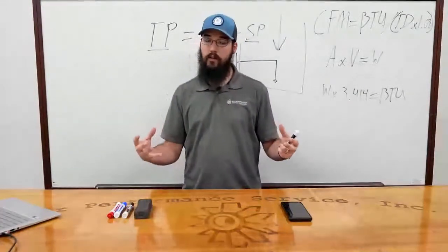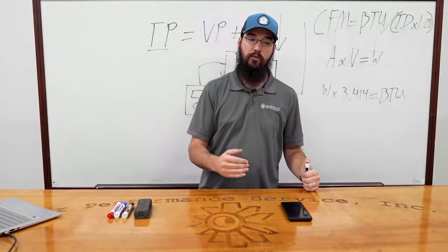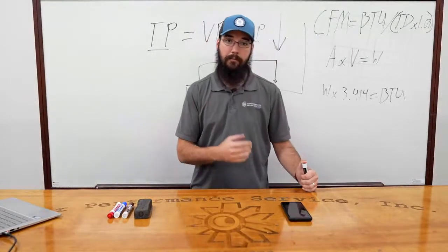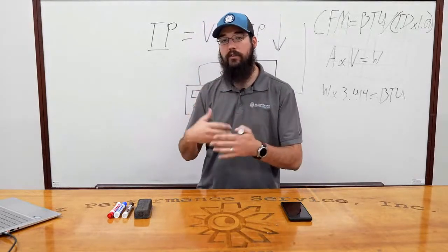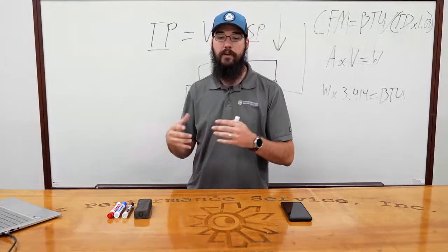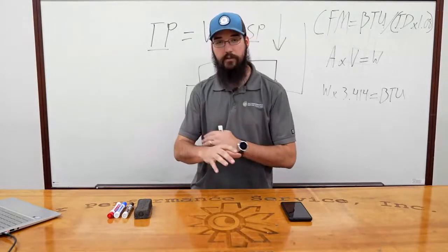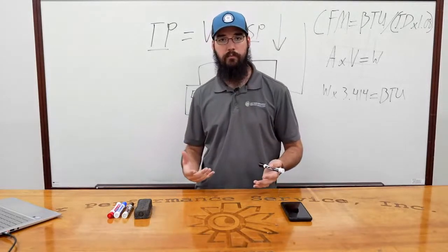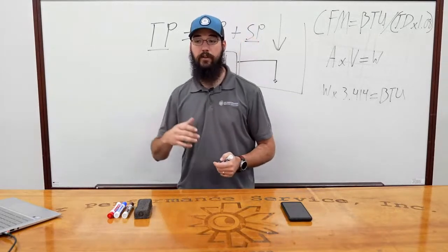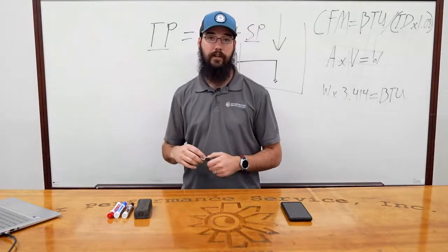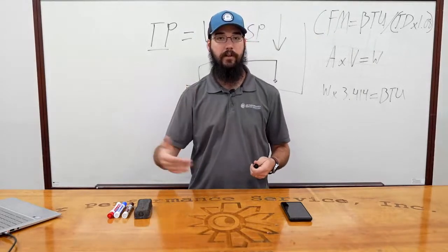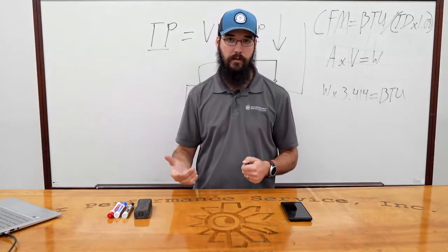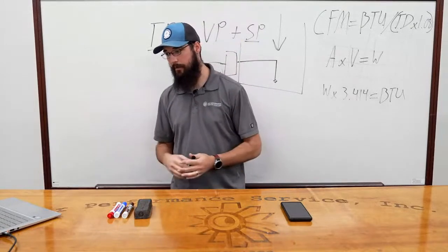And same thing on the low airflow side. We can remove too much humidity, and people can have a lot of sinus issues, and it leads to other health problems because the air is so dry. It dries out their skin. Everything's uncomfortable, just in the other direction. And so they run really high thermostat settings because they're trying to be comfortable, and they're trying to fix a humidity problem by changing the dry bulb. That's all the thermostat's really doing.